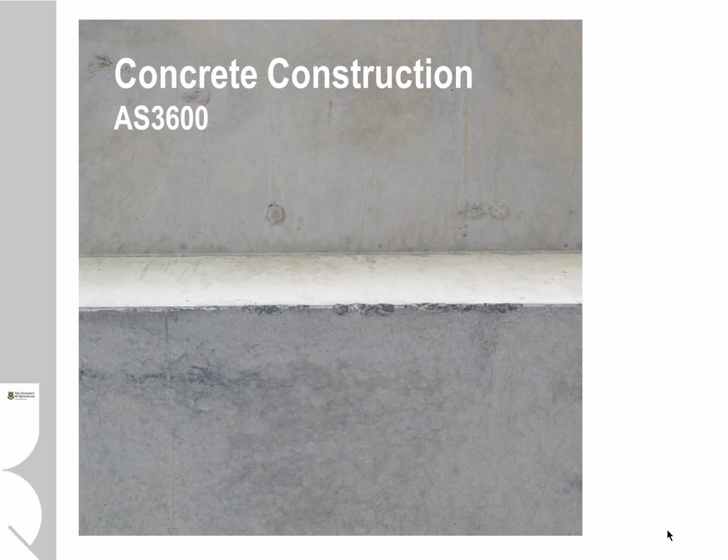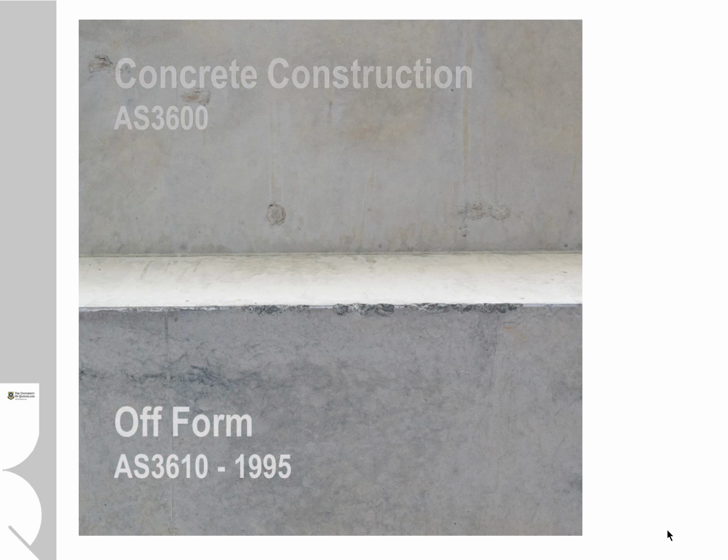I guess to an architect and to a designer, the smaller off-form concrete standard AS 3610 is perhaps one to pay not more attention but to be aware of, because in that standard it does set, I guess, the quality control of how to specify different off-form concrete finishes.